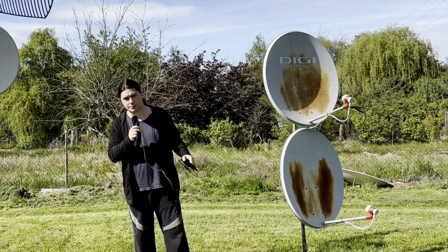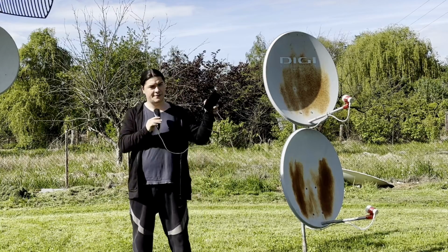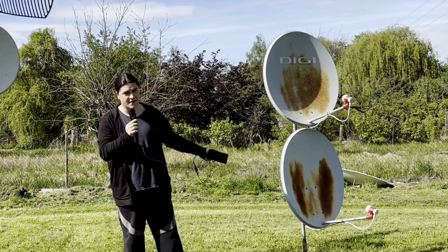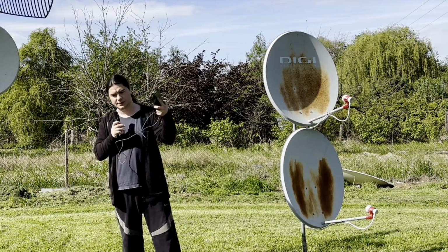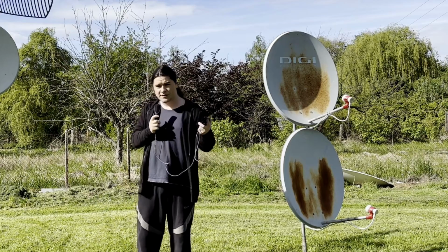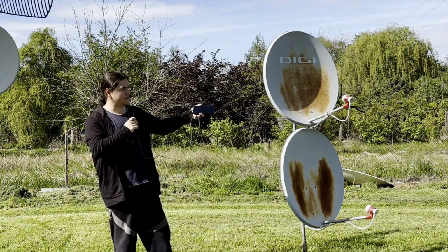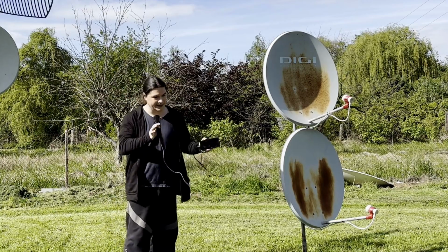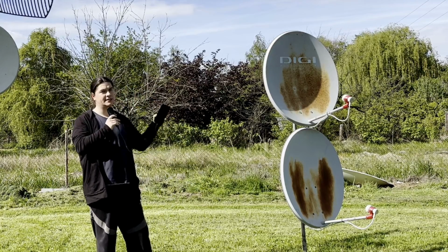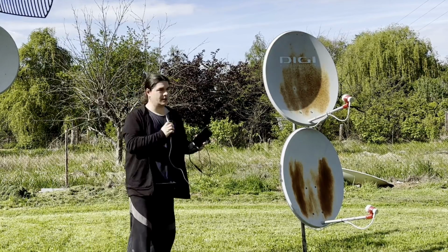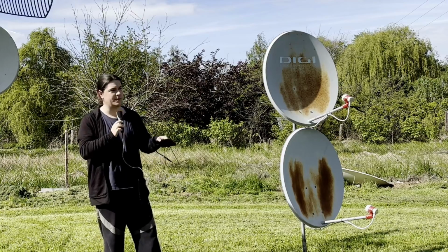Another thing is the direction or polarity of the power injector, where you have 3 connection ports. You have your DC connector, which is where the DC input comes from. You have an RF connector, which doesn't let any DC through, and then you have an RF plus DC connector, which is where the DC current gets injected. Obviously, the RF plus DC side has to be facing the LNB. You do not want to send 12 volts DC into the RF input connector of your SDR.